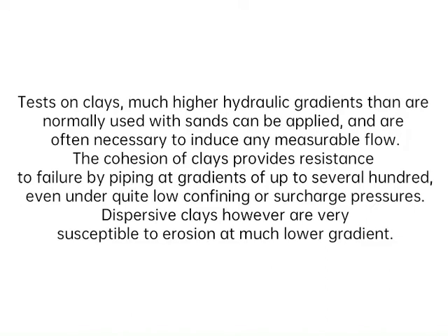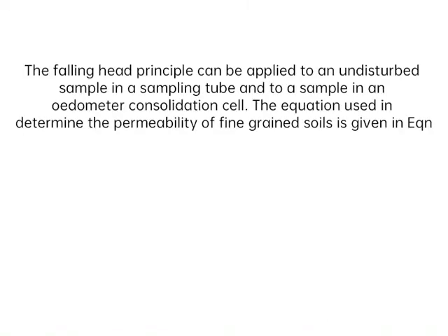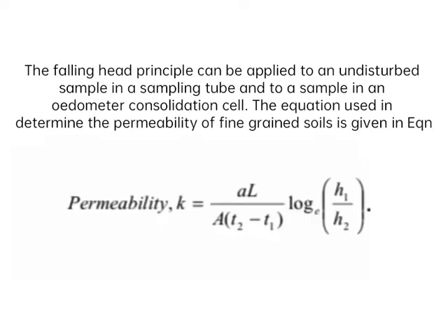Dispersive clays, however, are very susceptible to erosion at much lower gradient. The falling head principle can be applied to an undisturbed sample in a sampling tube and to a sample in an oedometer consolidation cell. The equation used in determining the permeability of the fine-grained soil is given.